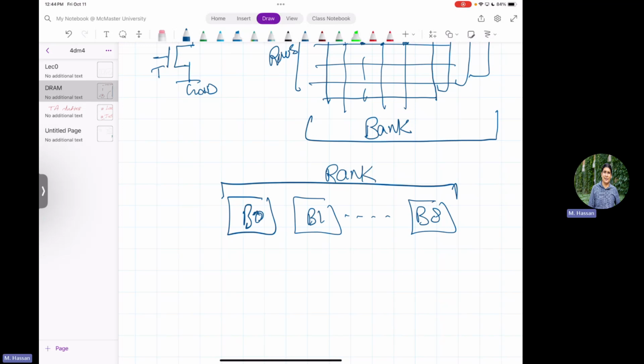Okay. Physically, if you have ever seen a DIMM, it's called DIMM because you have in fact modules on both sides, right? On one side of it, you will find 8 chips, and those 8 chips together can constitute a rank. So you have rank 0 on one side and rank 1 on the other side. Good. We'll discuss now why we need ranks and channels, but one philosophy of designing DRAM is you try to have a hierarchy of levels to increase parallelism as much as you can.